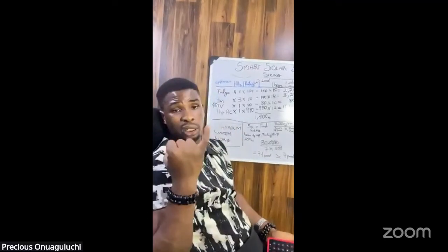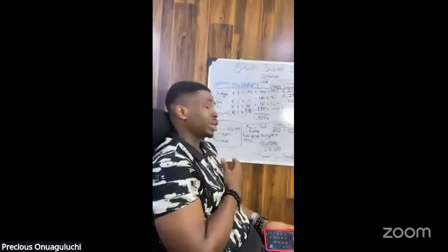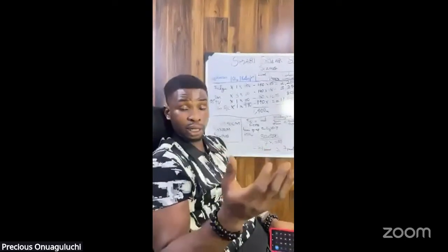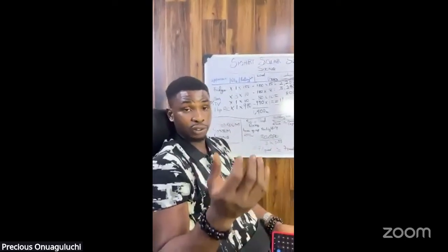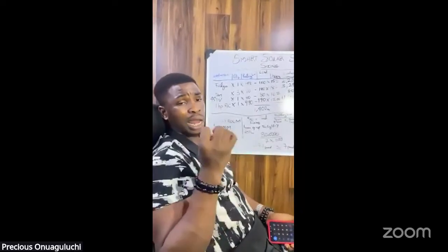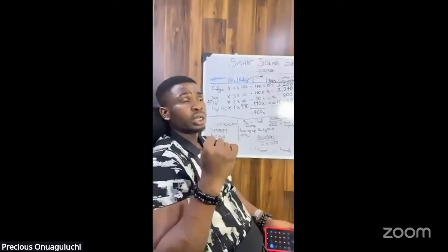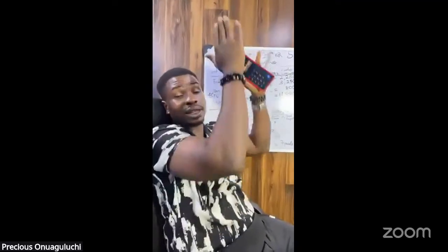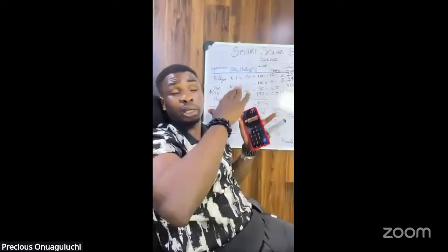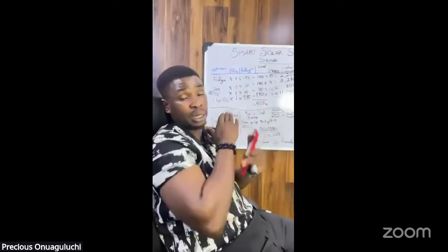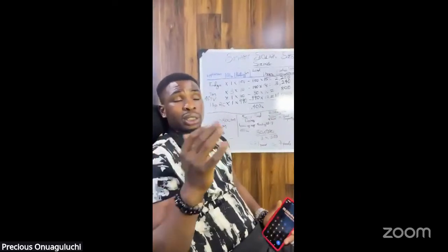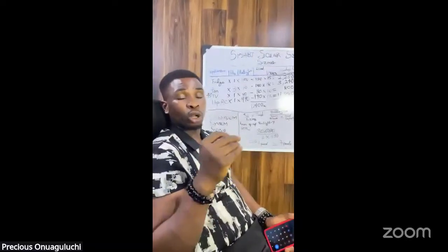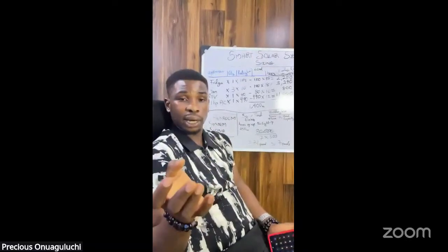This assumes that a 600 watt panel will produce 600 watts every day, always, for 7 hours. But it does not account for panel inefficiency. It does not account for the fact that your roof is slanted down, almost standing up, so the sun is not hitting the panel at the right angle. It's not factoring in that some panels might be shaded and you might not be getting optimal sunlight.